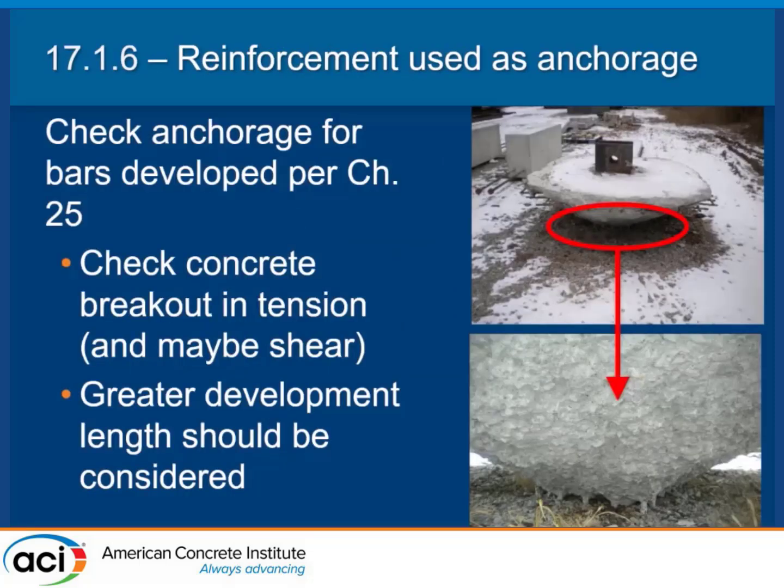And here's a case where I was saying you can use reinforcing steel welded to the bottom of a plate if you want to, right? You don't have to use all these other anchors, but when you do, here's a case of a radio tower. I had big guy wires that came down and they were anchored into just big hunks of concrete. You can see it's fairly substantial, this is a big hunk.